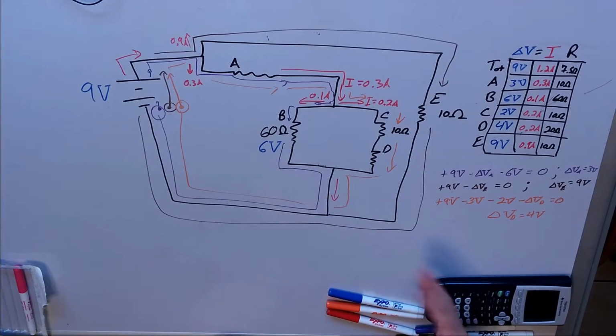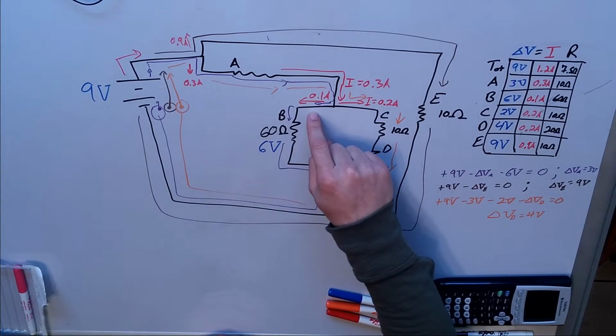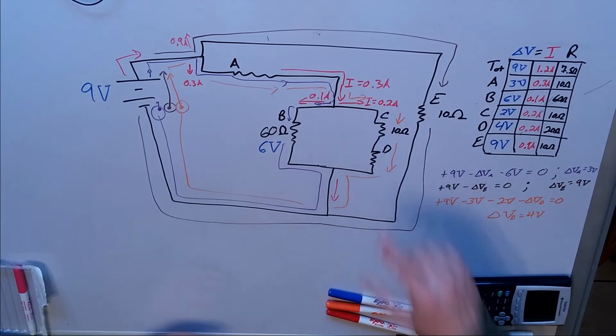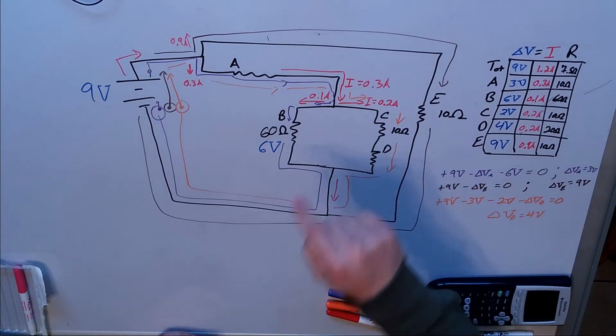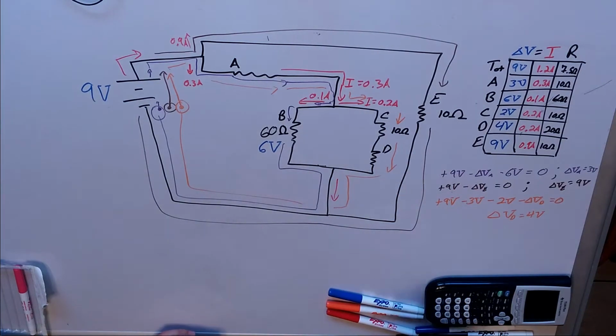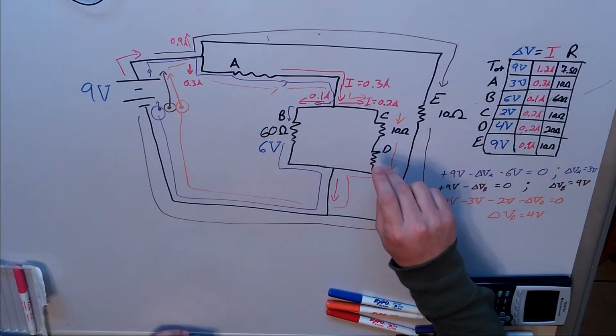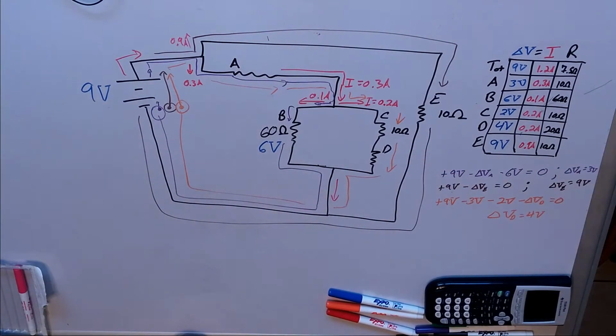This is also something, as you're working through it, if you know that 1/3 goes this way and 2/3 go this way, when you get used to it, you could also come to the conclusion of, oh, this must have half of the resistance of the other side, and therefore the unknown quantity is 20 ohms. So those are some things that when you start getting used to this more and more, you might be able to cut some corners. Now, that can be kind of tricky, and it really only works if you've got really nice numbers that are working out. But neither here nor there.